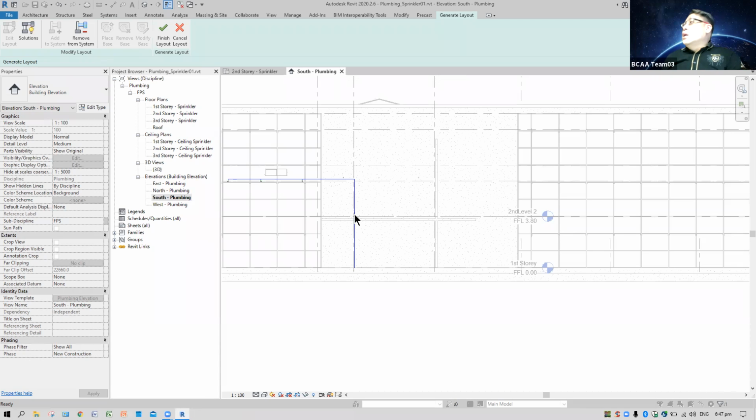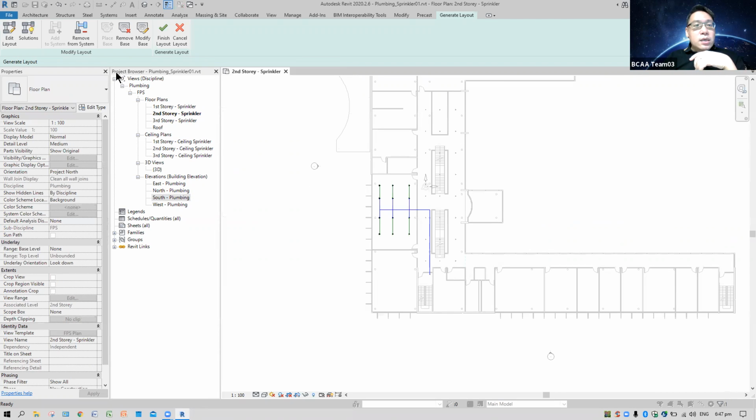That means civil engineering, when they need to know that there's a pipe coming, they typically dig, lay the concrete or foundation or whatever, then they lay out the pipe nicely first. All this must be preempted, then they can actually build inside. So this is okay, and my setting here has no change. When you click modify base, you can see that there is no offset. It comes exactly from level 1, so it's correct. So piping, I'll leave it at 150, no change.